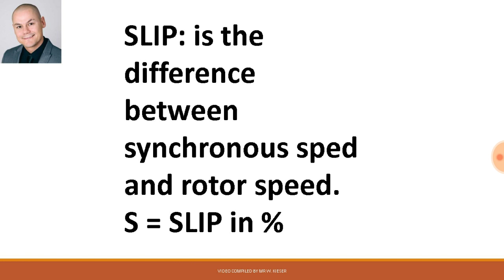Slip is the difference between synchronous speed and rotor speed. Now, if there is no difference between the rotor speed and synchronous speed, we'll find that no EMF will be generated. Therefore, there always needs to be slip in order for EMF to be induced.